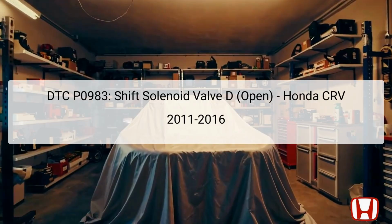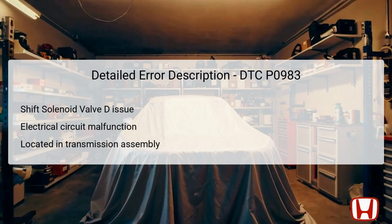The diagnostic trouble code DTC P0983 specifically refers to an issue with shift solenoid valve D, indicating an open circuit. P0983 indicates that there is an open circuit in shift solenoid valve D, which is crucial for automatic gear shifting in the Honda CRV. This solenoid plays a vital role in controlling the transmission fluid flow, enabling smooth transitions between different gears based on engine load and speed.